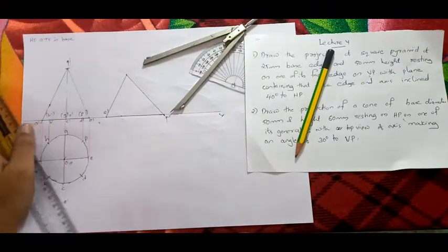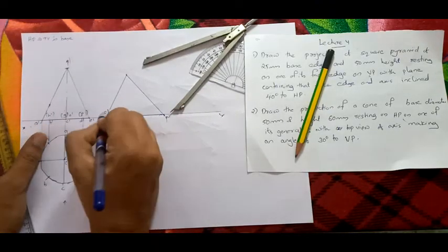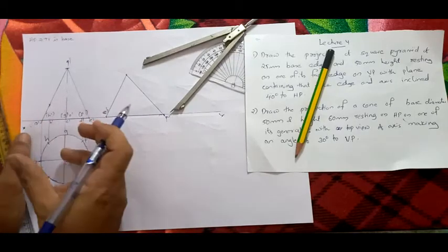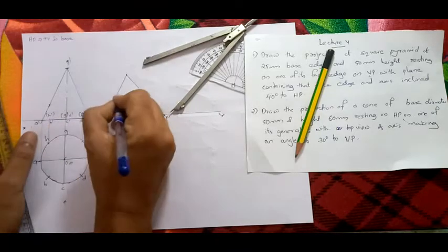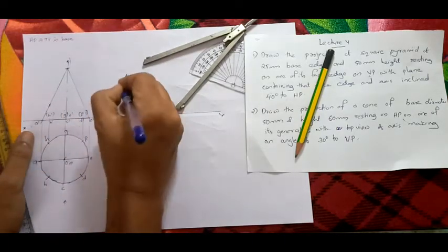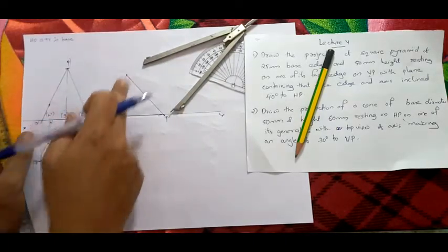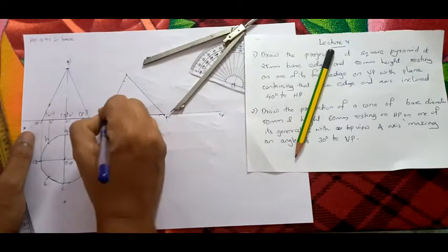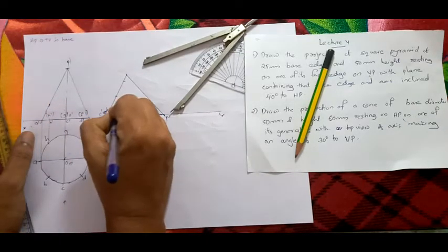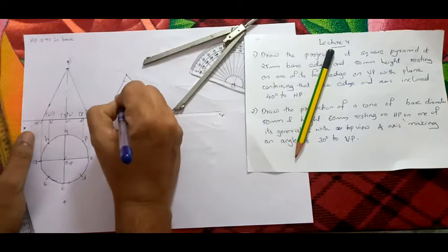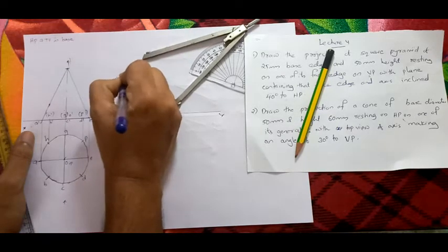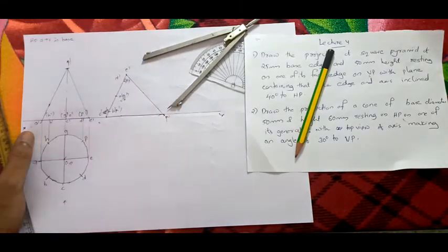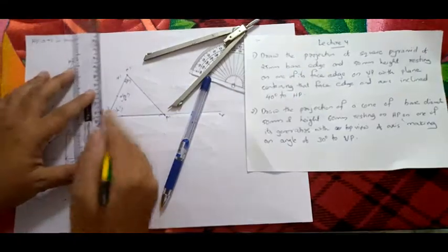So now you have to find these points. I will be quickly drawing through this. By using a compass you can find, right? You have to cut like this. From here you can cut and find the center point. Similarly you have to cut and find, by using either a scale or a compass, these points. So this will be E dash, this will be B dash, H dash, this will be O dash, G dash, C dash, this will be D dash, F dash and finally E dash. Now you have obtained all the points.